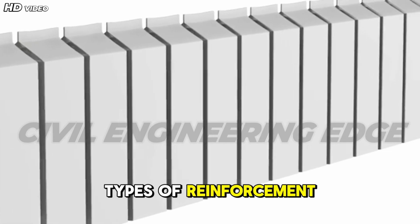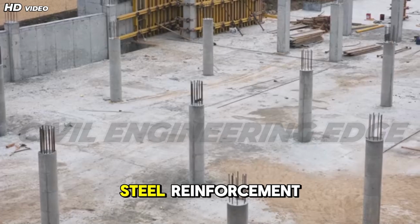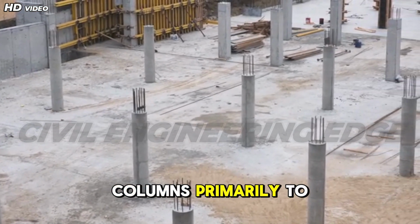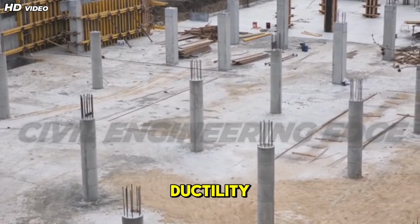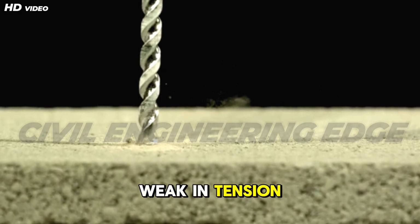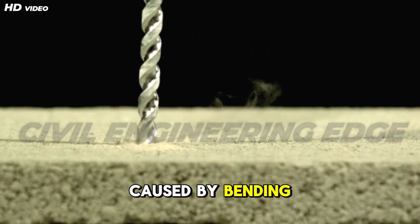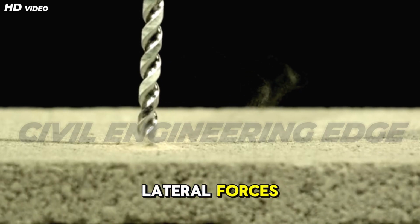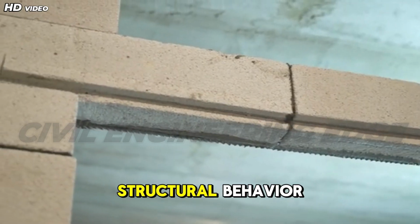Types of reinforcement bars and their role in resisting tensile forces. Steel reinforcement is introduced into concrete columns primarily to resist tensile forces and enhance ductility. Since concrete is weak in tension, reinforcement bars carry tensile stresses caused by bending moments, eccentric loads, and lateral forces. They also help control cracking and improve overall structural behavior.